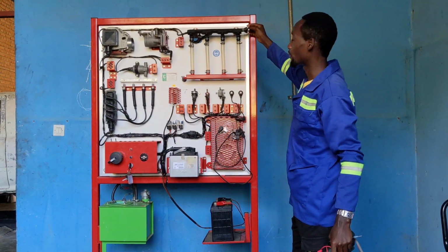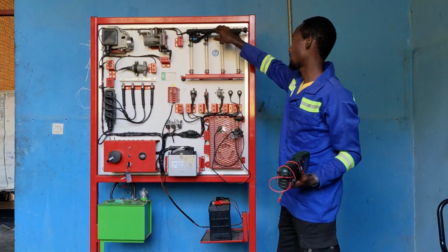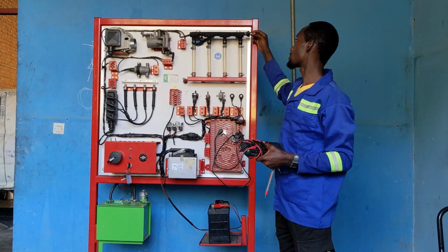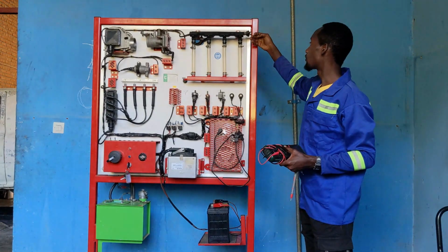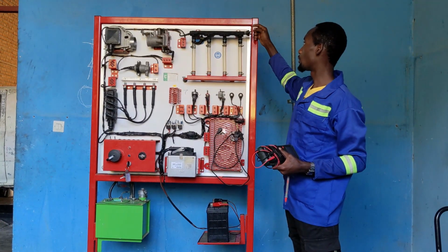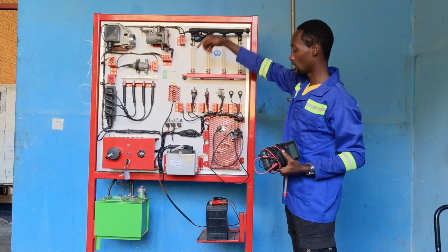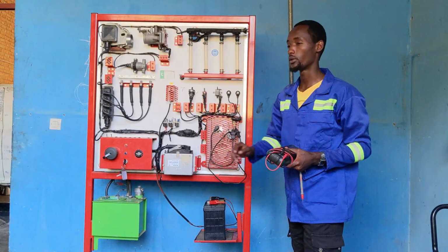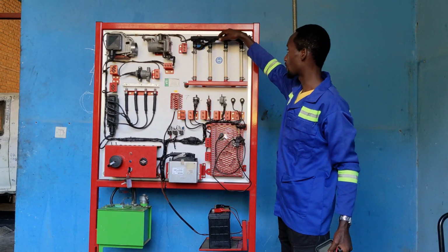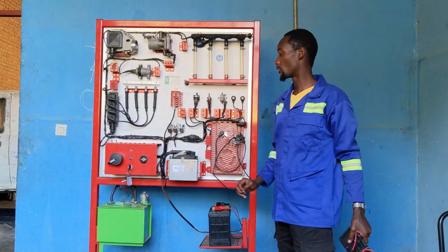So there is the pressure regulator. It is just used to regulate the pressure inside this common rail. If the pressure exceeds, it operates. There is the diaphragm. If the pressure exceeds, it pushes the diaphragm and spring, then opens the passage of this return, and that excess fuel is returned back to the fuel tank or fuel reservoir. So there is also a return fuel line from this common rail. When the pressure exceeds, it also returns back to the fuel tank.